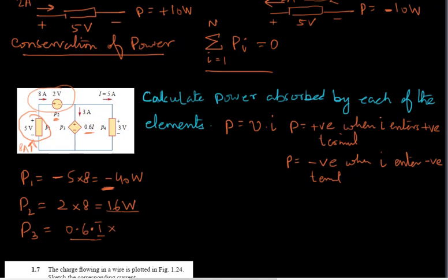The current is 3 ampere. And according to the passive sign convention, we need to understand that the 3 ampere is entering the plus terminal, which means positive sign. And this is going to give you the power consumed by this device or generated by this device. And you can see I is over here. We need to find I in the circuit, and that I is 5 amperes.